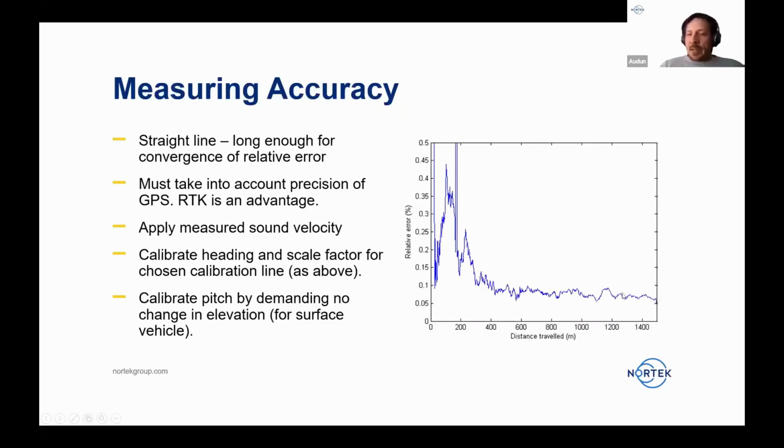So at the very end of it here, where I've stopped, now I'm at about 0.06% maybe. So that's the bias on this particular line. So when measuring long-term accuracy, that's the number I'm looking for. However, in order to characterize the DVL, I would really like to do this multiple times to get some statistics on it, because we know that the bias might vary with conditions.